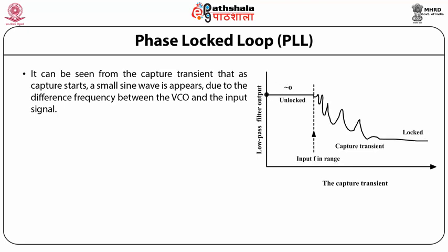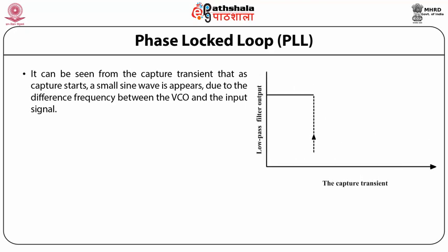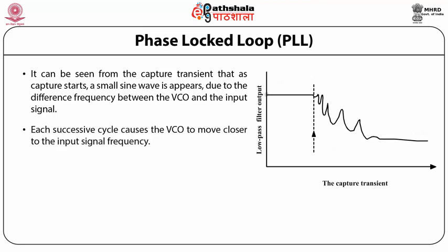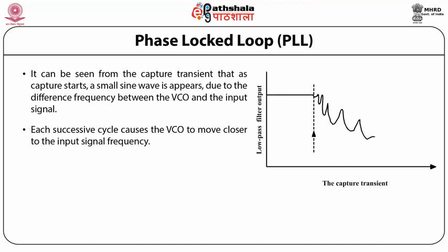The DC component of the beat drives the VCO towards the lock. Each successive cycle causes the VCO to move closer to the input signal frequency.